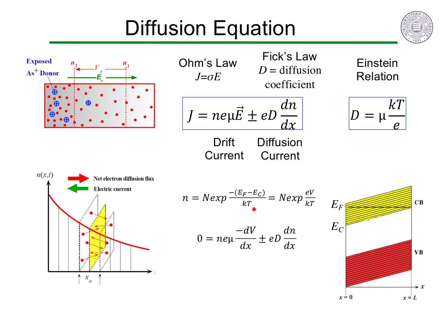Equilibrium also requires the drift current to exactly cancel the diffusion current. This requires the mobility to be related to the diffusion coefficient times the relative change in N per change in V, which becomes d log n dV. This is simply E over kT, giving the Einstein relation. The relationships for electrons and holes are similar, where we generally have different mobilities and therefore different diffusivities for electrons and holes.